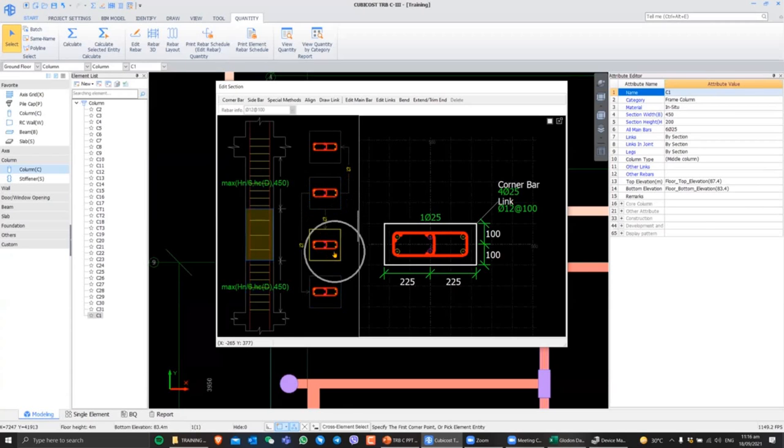Pagdating po sa rest spacing sa gitna, medyo maluwag, no? Basically mas madali, mas less yung shear stress natin dito. So mas maluwag. Let's say 12 at 300 siguro. For example lang po, no? 12 at 300. Okay? So right now, since I unchained this, I'm allowing the software to specify different informations on every densification of my column. Okay? So that is how we edit the densification.